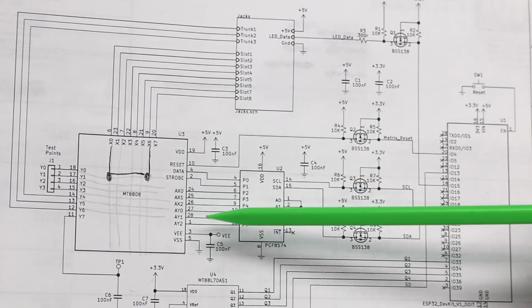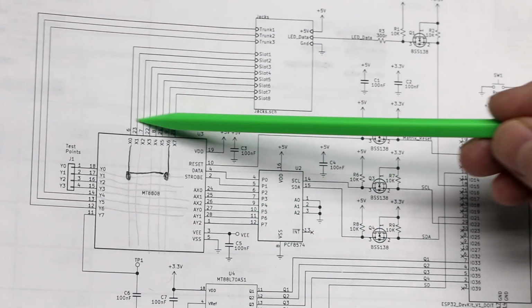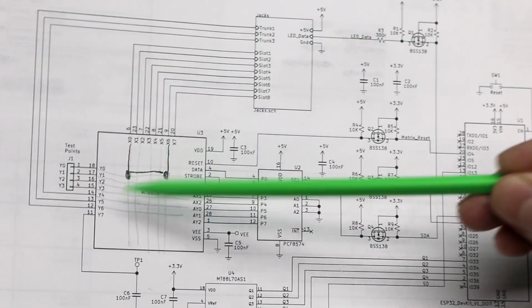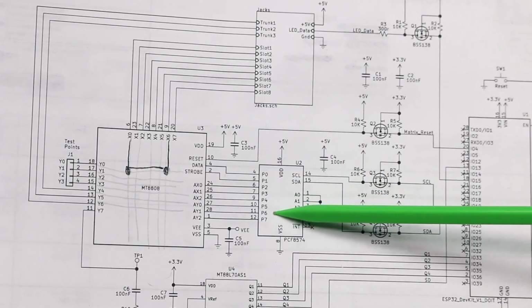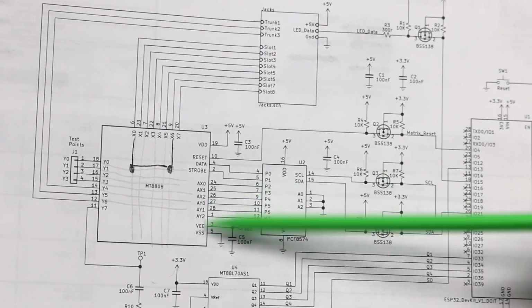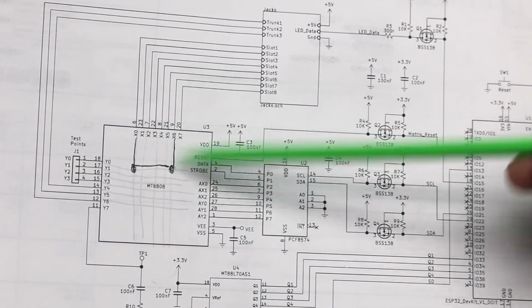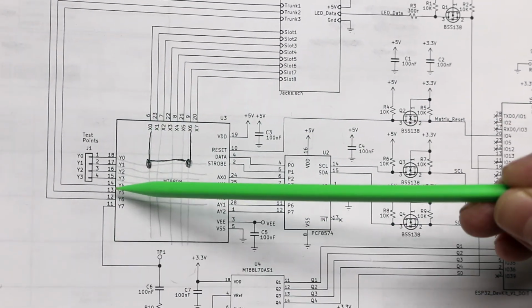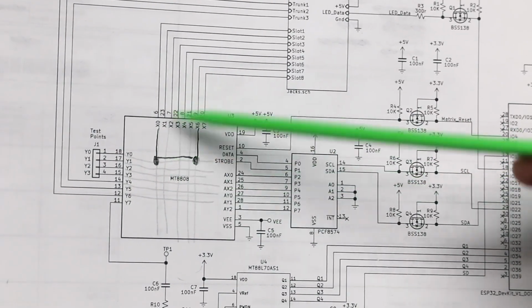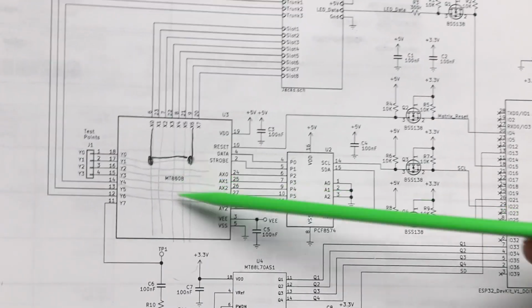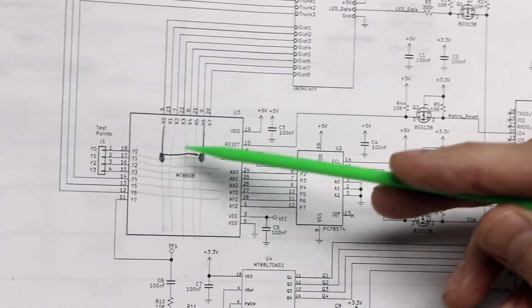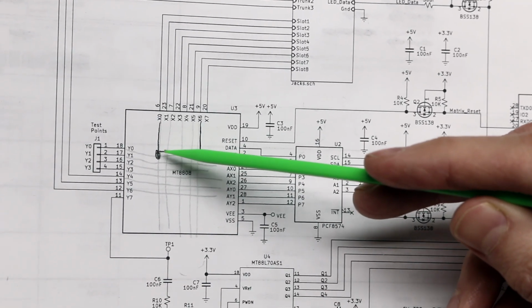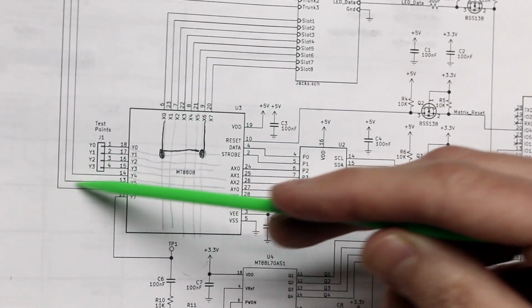So basically, all we need to really focus on for the principles here is this analog matrix. So when we do want to route analog signals through, the ESP tells the GPIO expander over I2C what control pins to set to make new analog connections. So here we have 8X and 8Y paths, which I've sketched in loosely as vertical and horizontal lines representing a grid of nodes inside here. So what this chip does is allow you to close the connection, making a circuit path between a certain X and a certain Y line.